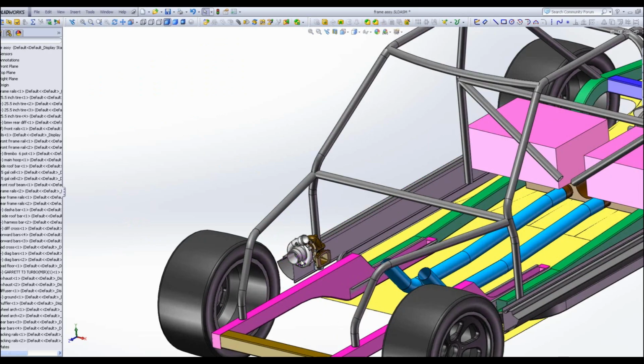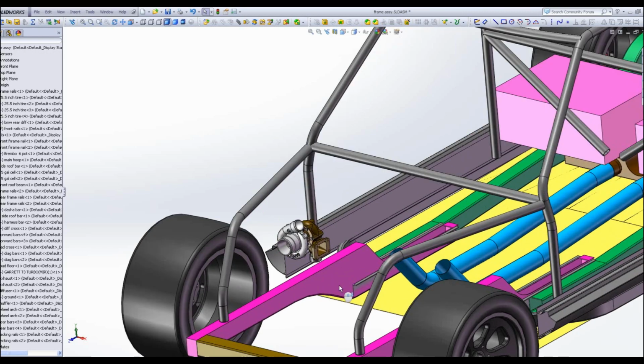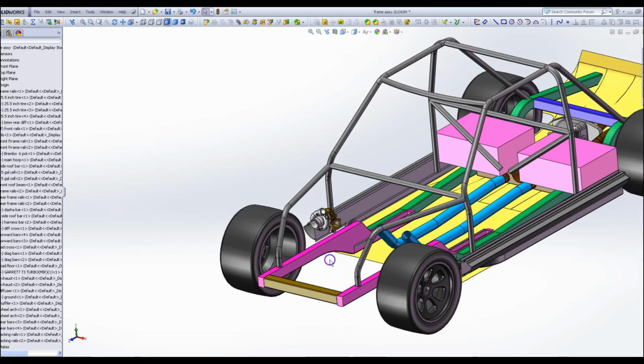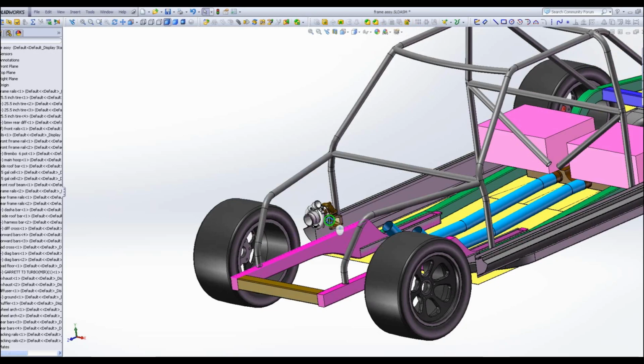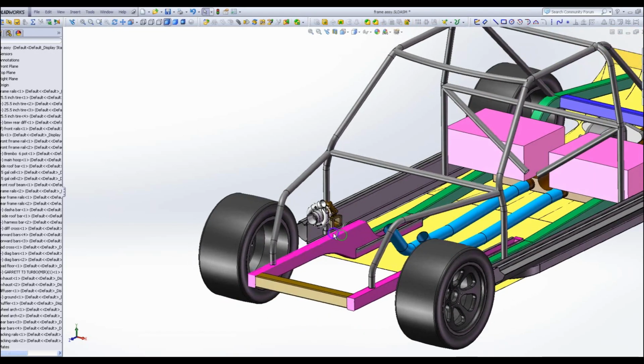This is not the right turbo, but a similar size turbo. I'm going to use a G25 660, which is capable of theoretically 660 horsepower, but in all practical purposes, more like 500, 550 maybe, if you want to run in the efficiency window, which kind of do.